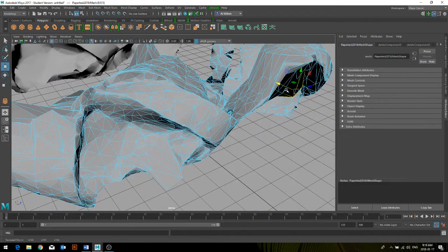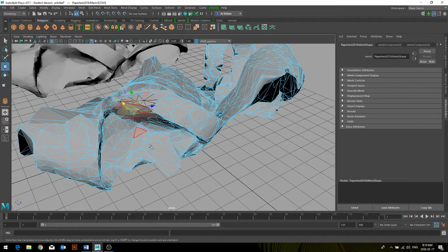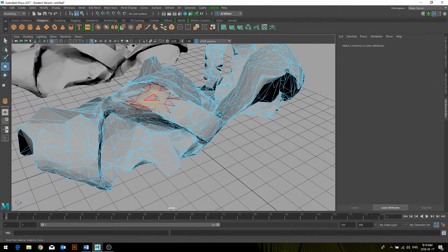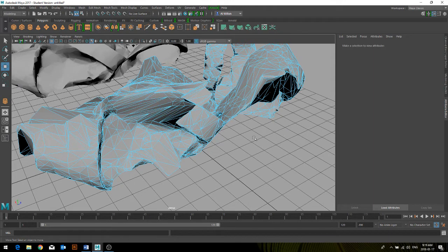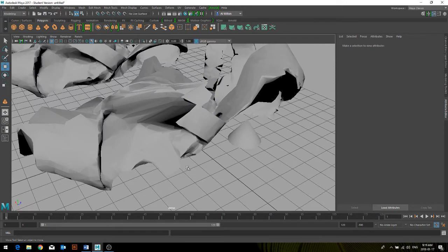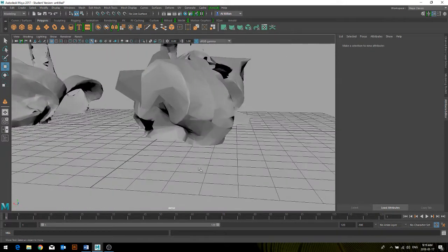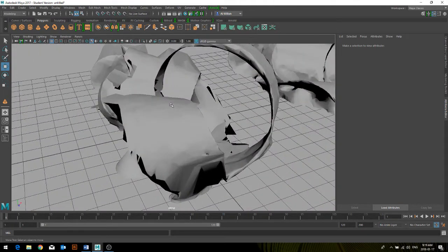One of the things to be aware of is if you begin to take a bunch of faces and pull them over others, like let's say we'll take a bunch of these faces and pull them through, you'll start to notice that some of these geometries show up as black, pitch black, and that could indicate non-manifold surfaces, or surfaces that fold in on top of each other.